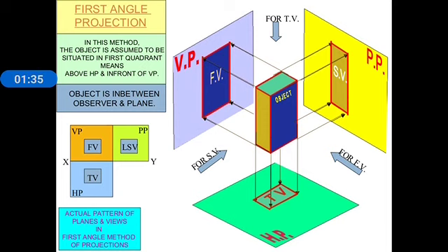So what things do you need for freehand sketching? A soft grade pencil, preferably HB or H, sharpened to a conical point, a soft rubber eraser, paper, and a book or pad. Only these things are needed to do a freehand sketch.